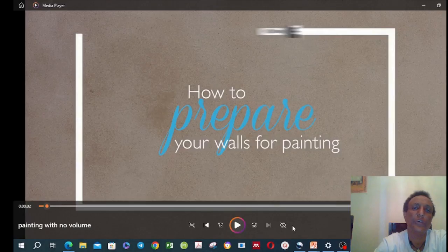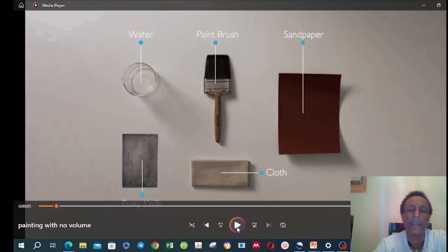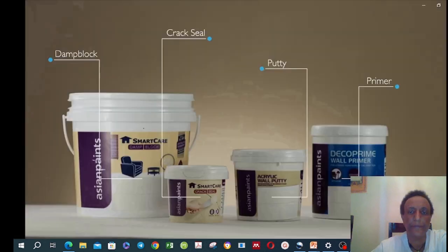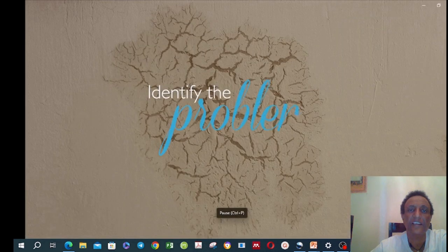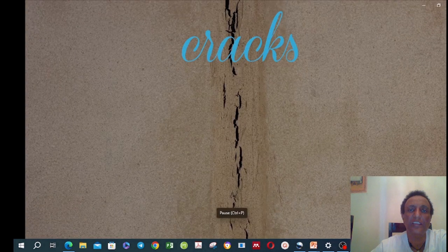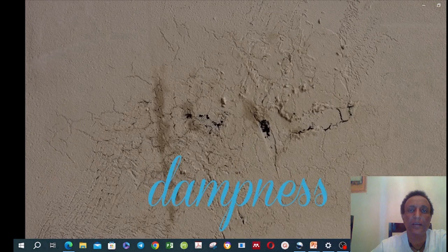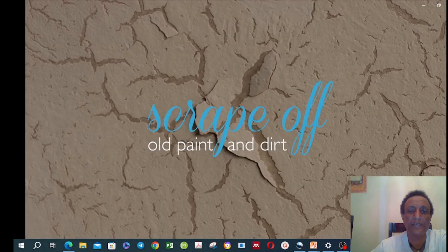This video demonstrates the step-by-step procedures of preparation of surfaces for painting. These are the materials for background preparation for painting: water, paintbrush, sandpaper, cloth, and putty knife. The first procedure is identifying the problem, that is, cracks and dampness.